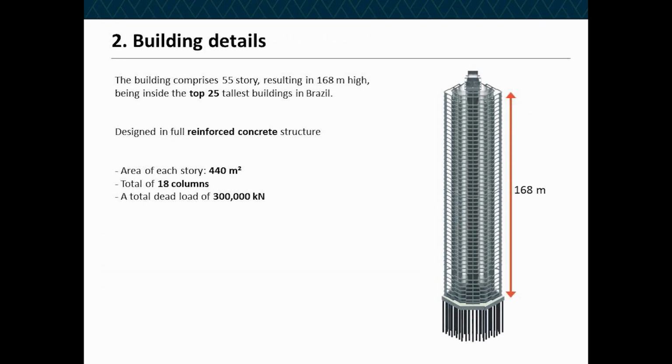So as I said, the building comprises 55 stories, resulting in something close to 168 meters tall, meaning then one of the top 25 tallest buildings in Brazil today. The whole structure is designed in reinforced concrete, which is the most common type of structure here in Brazil. Each story has an area of about 440 square meters. We have a total of 18 columns, which are actually structural walls because of their size, and a total estimated dead load of about 300 meganewtons.